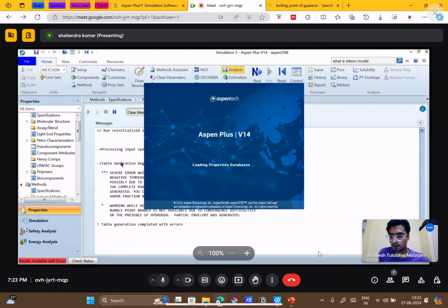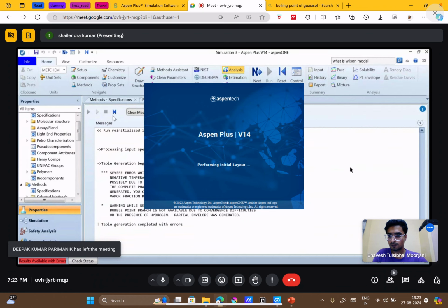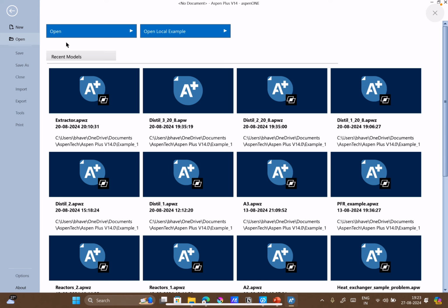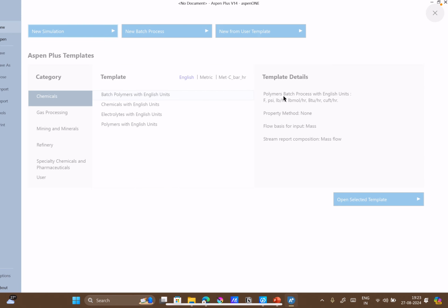Had you started it in a new simulation or were you utilizing the same file? It could be that the previous stuff has been causing this issue. Started with the new simulation. You have used a new simulation. Okay, so it could be some issue with the Peng-Robinson method or the mixture of ethanol and isobutanol.